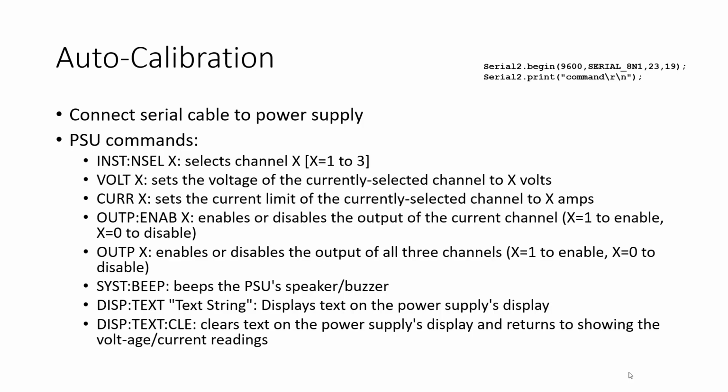And then this is out of date. It's updated in the lab sheet though. The pins are 13 and 14, right? 12 and 13. And the ADC pin is now 15 instead of 34 as well. Yeah, so this is updated in the lab sheet. It's just the slides that haven't been updated yet.